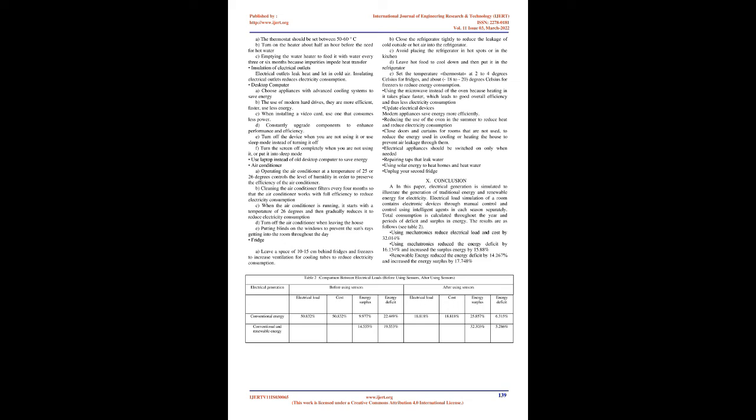9. Methods of reducing electrical power consumption in campus. Lights. A. Turn off unnecessary lights or when leaving the room. B. Use low bay lights in places not used for reading, and other areas where bright lighting is not needed. C. Using LED bulbs to save electricity. D. Avoid using halogen lamps, which waste electrical energy. E. Clean the lamps from dust regularly so that light levels do not go down.